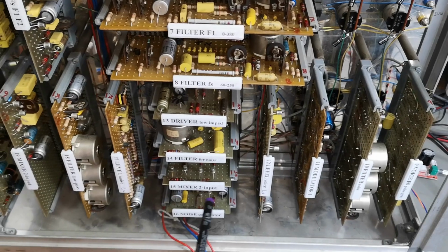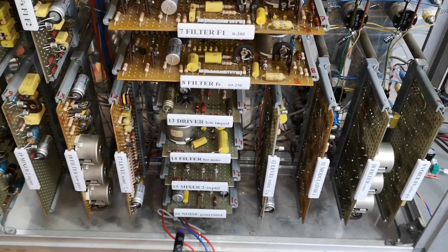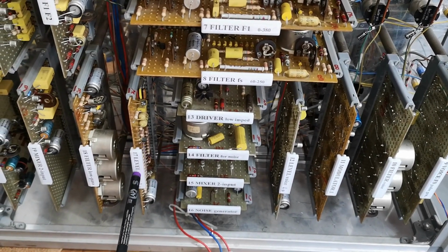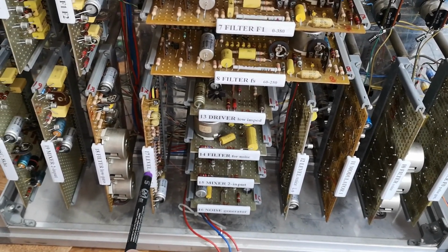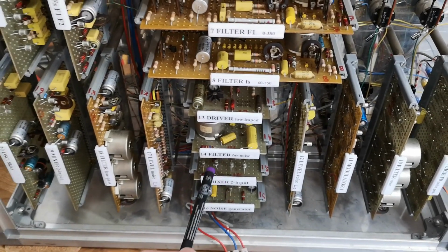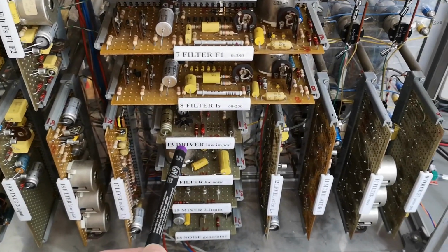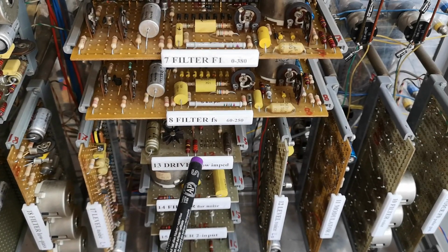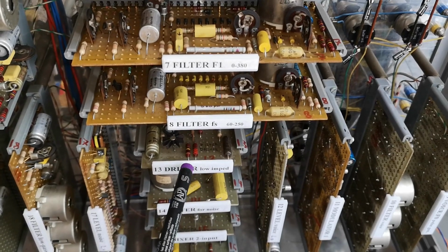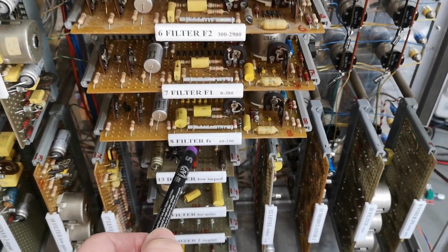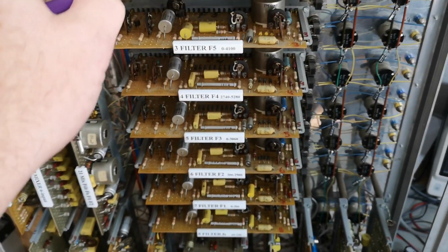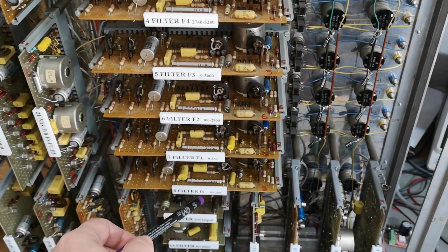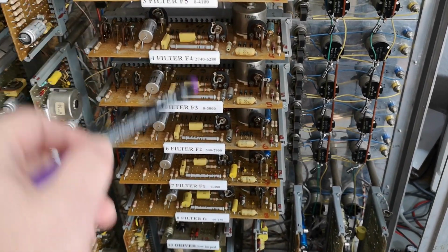This is now mixed together with a noise generator. The noise generator goes to a level, variable level, and then this is mixed with the filters and the low level, a low impedance driver. So this is a 4.7 ohm output driver that drives all the filters for all the different frequencies and different levels of overtones you want to have.